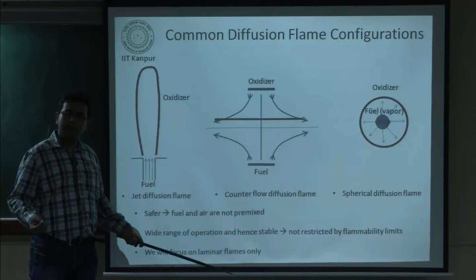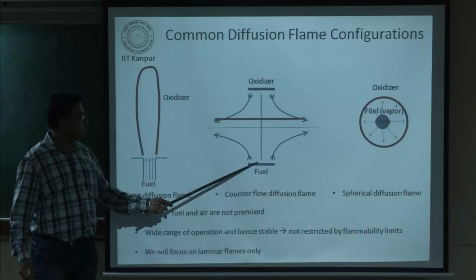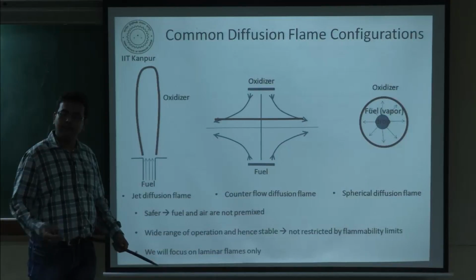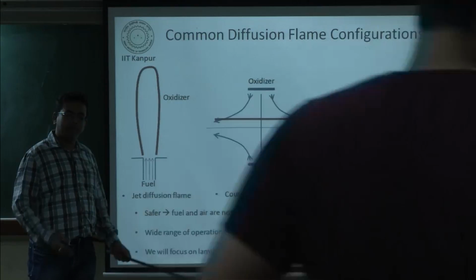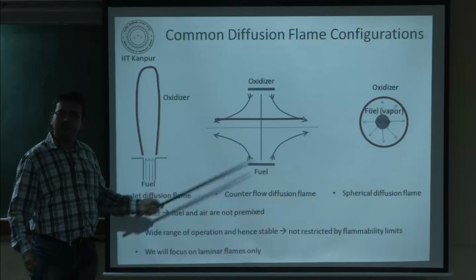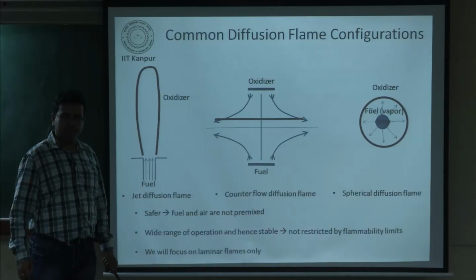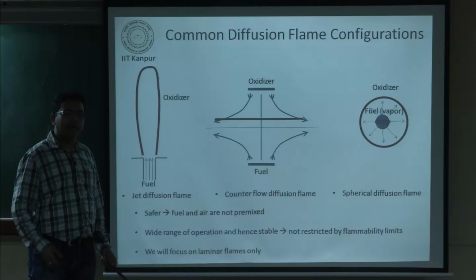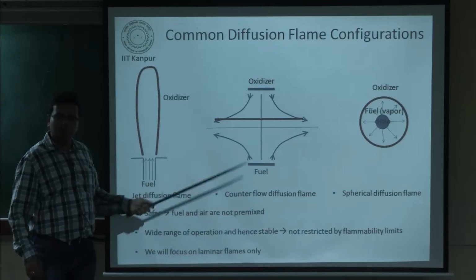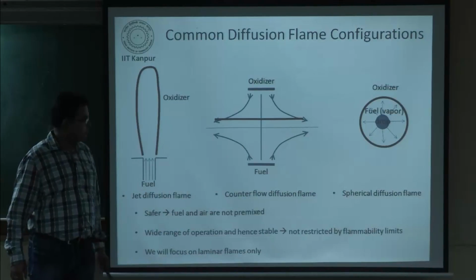Now if you can come up with the mixture fraction from these concentrations of different species, right, then you can get a very good flame structure. Then you can represent all these variables, like temperature and the species concentrations, in terms of mixture fraction. Okay. So that will give you some idea about the flame structure. We are going to see that when we talk about the counterflow diffusion flame. Okay.